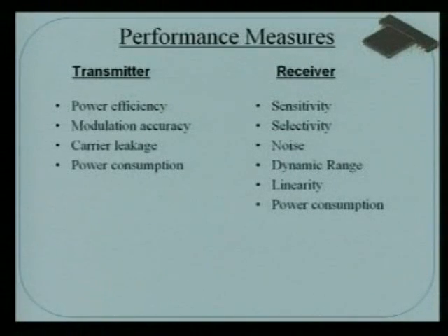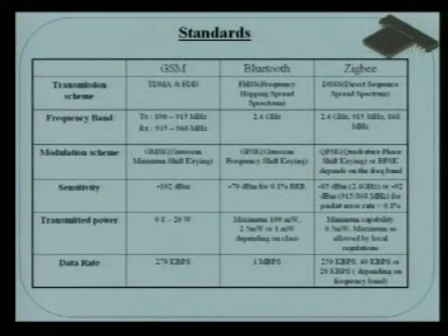And if you look at the receiver, there is selectivity. You have to select a particular channel. I want to listen to only your voice, not your friend's voice, because all the signals are here. Your mobile phone is actually catching all the signals, but I am only detecting your channel. The tolerance of this frequency selectivity is even a few kilohertz, where 2.45 gigahertz is my carrier frequency. Think of the kind of circuit complexity. Then I also mentioned linearity and so on.